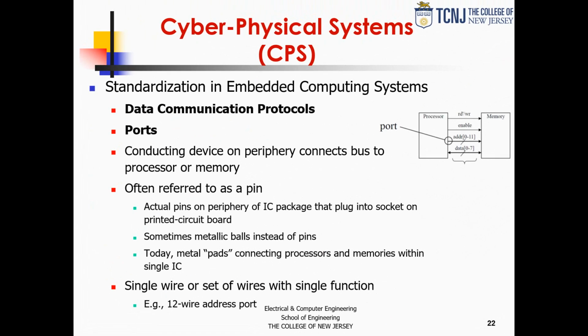Question. For the last slide, or just even here, what's that slash in the middle of the path for processor to memory on the address and data? Very good question. So the question was, what is this slash here in that single line? That means that it's a multi-bit or a multi-line bus. In this case, that line signifies that it's really eight connections from 0 through 7, and this one would be 12. So that's what the symbology means.